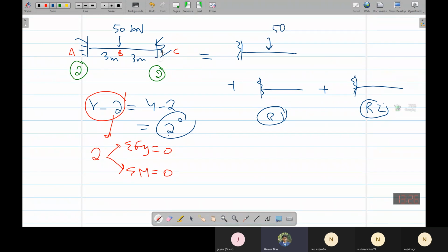So in this case, we remove the vertical force at C as well as a moment at C. So in the redundant structure, we'll just put these here. This is Cy, and this is MC. Okay. Where we remove our support, we just place a reaction at that place, and the magnitude of that reaction should be 1. It should be a unit load or unit moment.